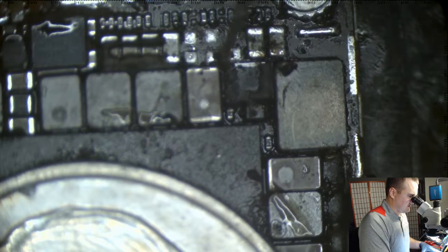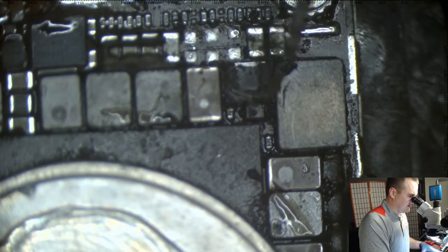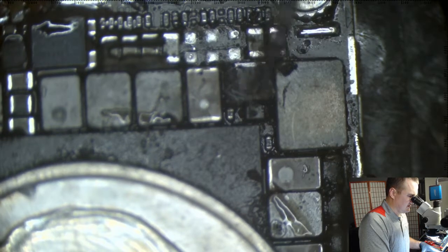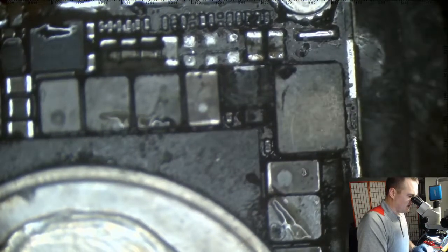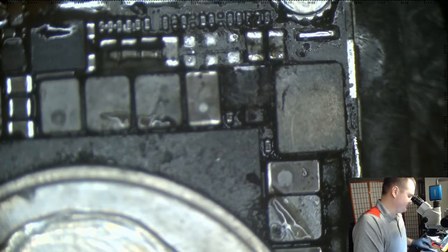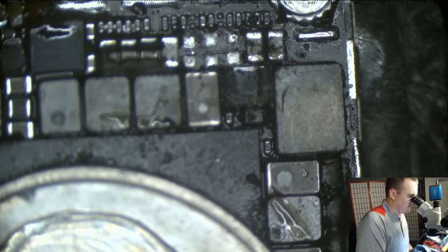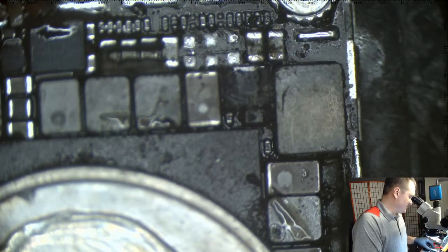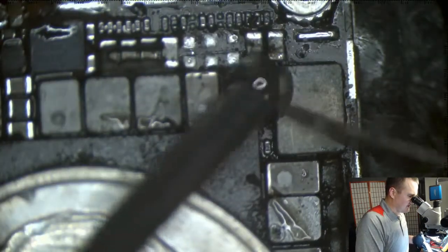Okay, next thing to go, I'm going to take this boost coil out. In my experience, sometimes you can replace your blown out diode and your shorted cap and your melted coil and just leave the boost chip there. Most of the time it dies too with all the other stuff that died around it.